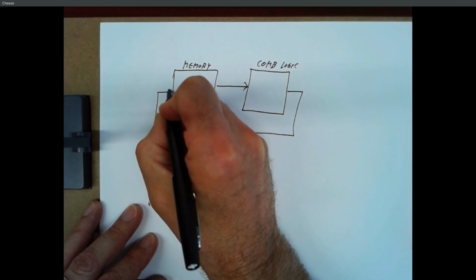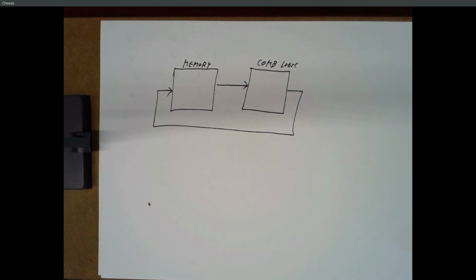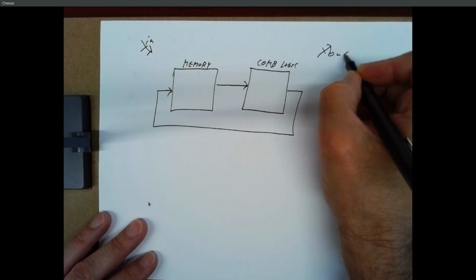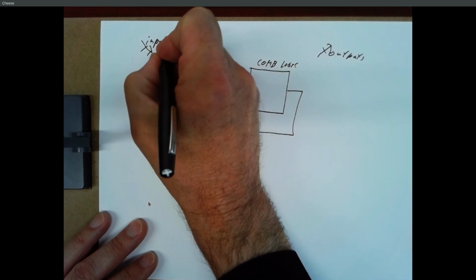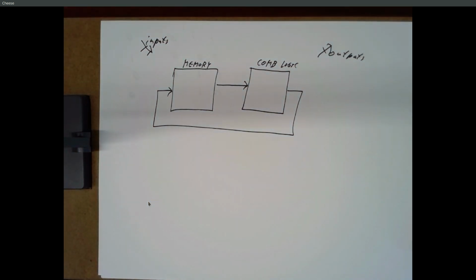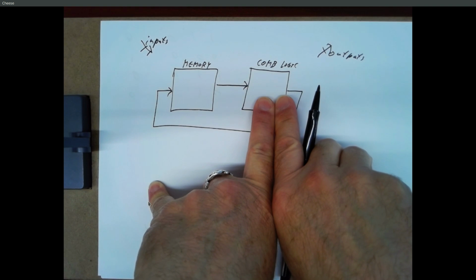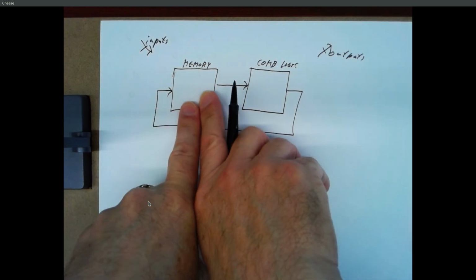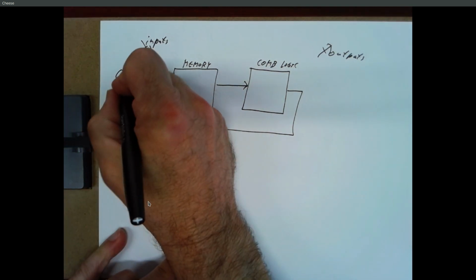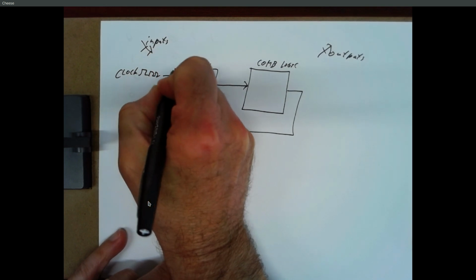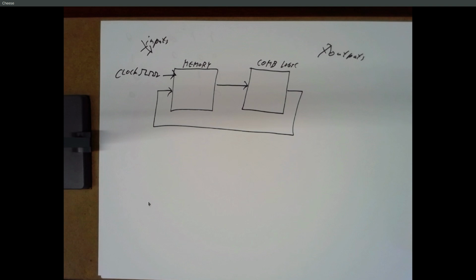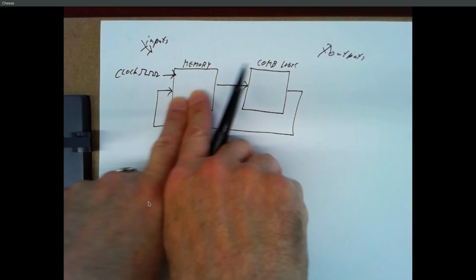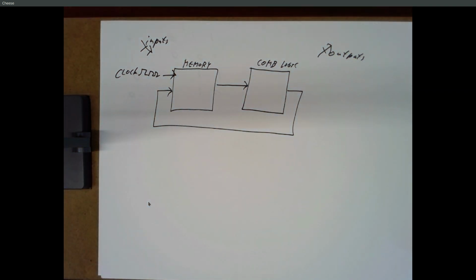And this is basically what your state machine looks like. There's some inputs and there's some outputs. But the real core of your state machine is basically a bunch of flip-flops and some random logic. The output of the flip-flops goes into this logic, the output of the logic goes into the input of the flip-flops. And you have a clock which tells the flip-flops to go to your next state based on your inputs. They go to a new state, get new outputs, that changes the combinational logic, it feeds back in, and that's how the system moves from one state to the next.